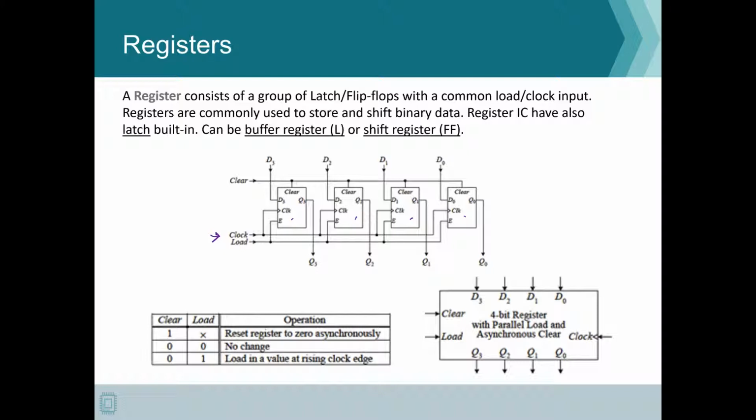In some cases, whenever you have a shift register, we also have some register ICs that have built-in latches. So you also have a shift register followed by a latch so that it can hold on to a value and you don't see the transitions when the actual shifting happens.